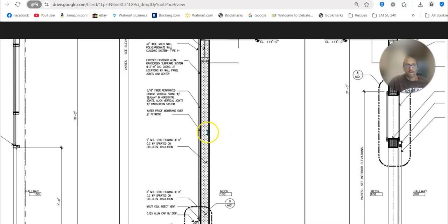and that's your total R value for the wall. And just keep in mind that in this wall, since there is a metal stud, there'll be basically two R values for this wall. One R value is for the area of the wall that has the metal stud cross section, and the other R value would be where, instead of a metal stud, you have 6 inches of spray foam.